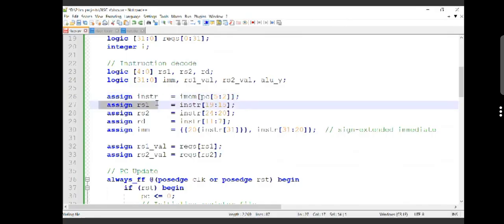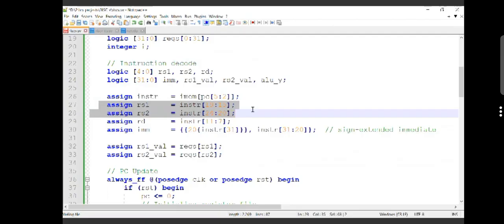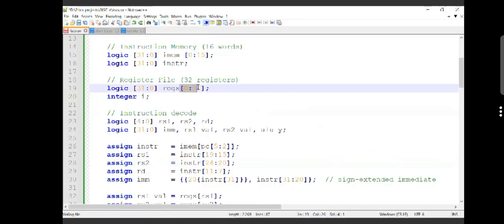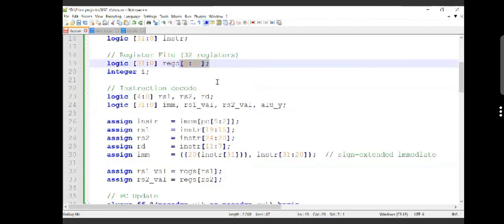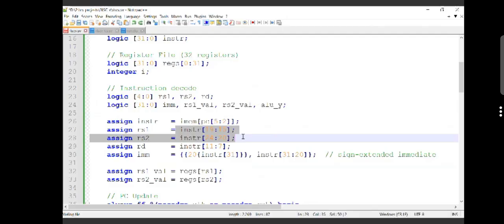And next up, you have two register sources. So for the two sources, you are giving the instructions. What are the instructions you are giving? You have an overall instruction of 32 bits, right? In that overall 32 bits, you are selecting the source and two source fields of the particular instruction. What are the particular fields you are selecting? 19 to 15 and 24 to 20, like source and two source. You are selecting two different types of fields.